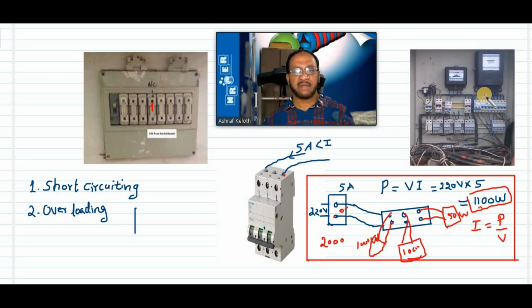And here you can see a main switch is there. See the main switch. In this main switch, the main live wire and neutral wire will be there. You have to give the connection to the main live wire and neutral wire, the main one. And then it is branched into many branches for different areas. Don't give connections at the branches; give to the main line.